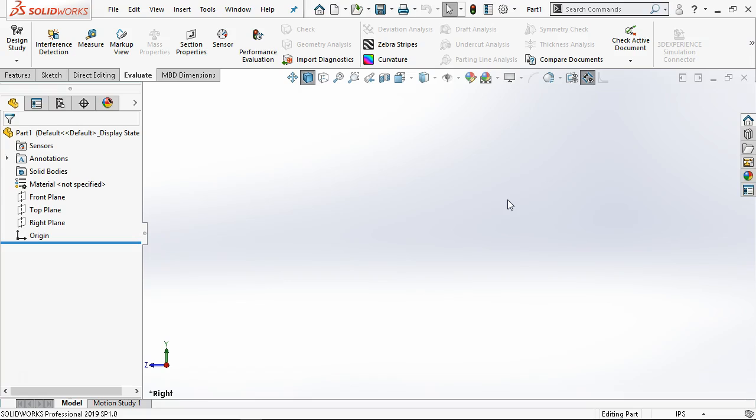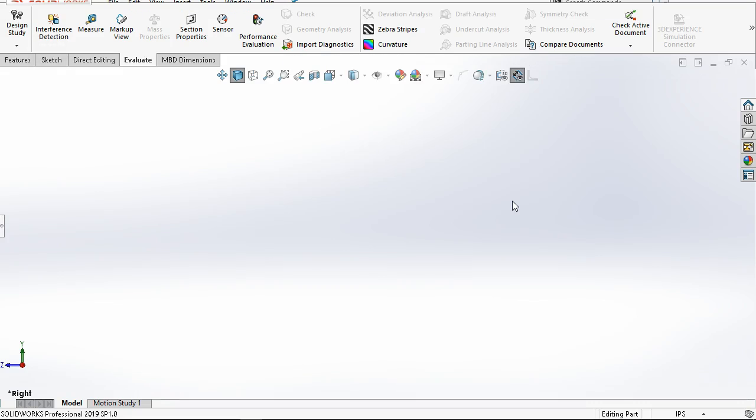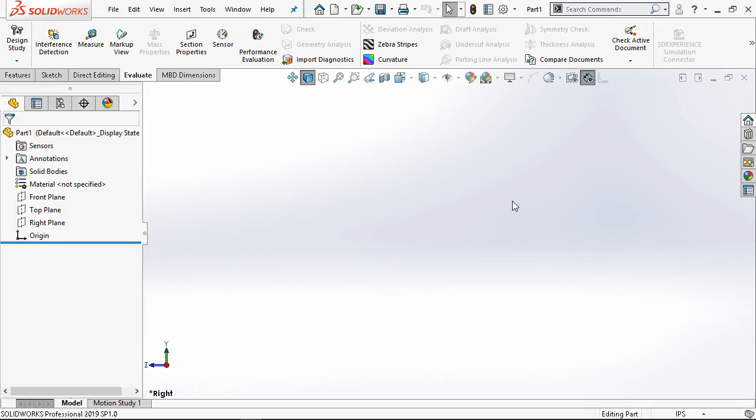So just be careful kind of clicking, and there are some F keys that when you go across the top of the keyboard, that will affect what we're doing. So for example, I think it's F11. Nope, that was my brightness. There we go. So F11 hides the feature tree property manager over on the right, or I'm sorry, over on the left.